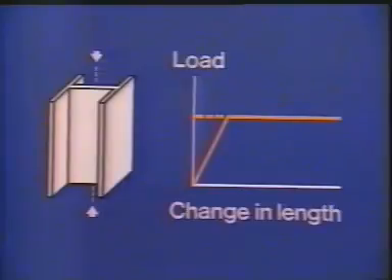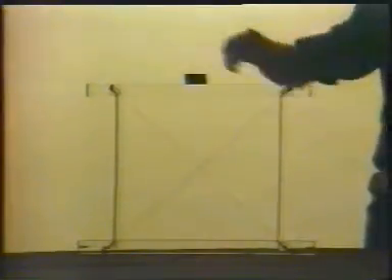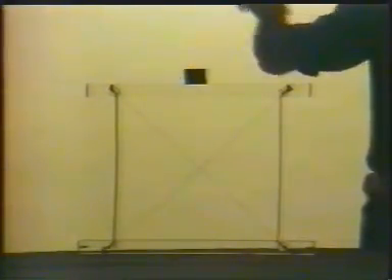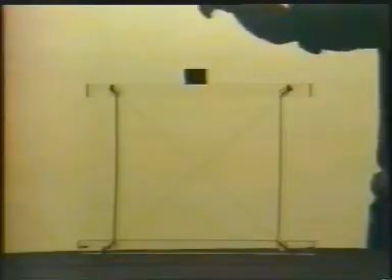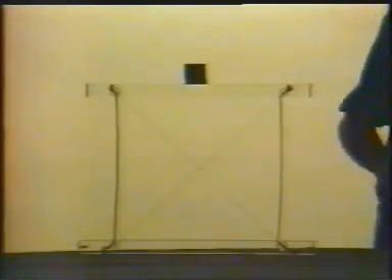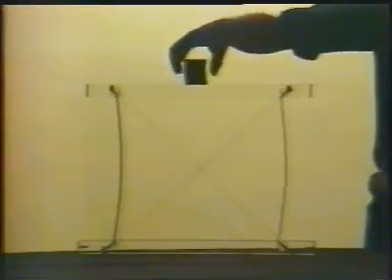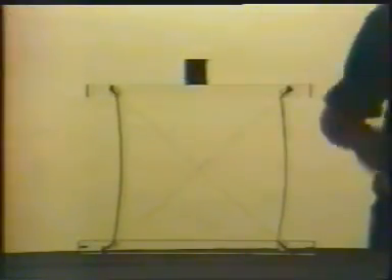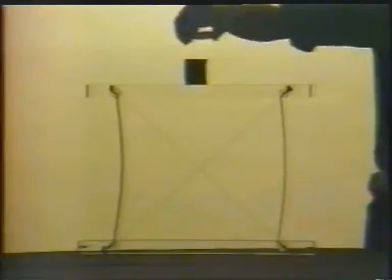The collapse load of a column is related to two limit conditions. A stocky column will fail by general yielding of the cross-section, and the column will squash. If a column slenderness is very high, higher than is found in normal fabrication, it will fail elastically without yielding. If it is initially deformed, failure will be accompanied by a gradual increase of lateral deflections.